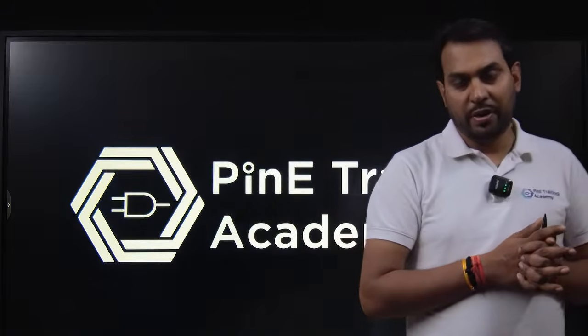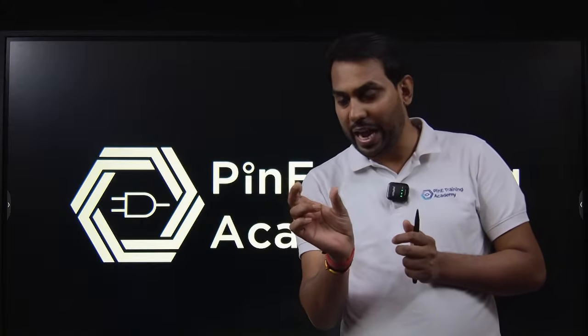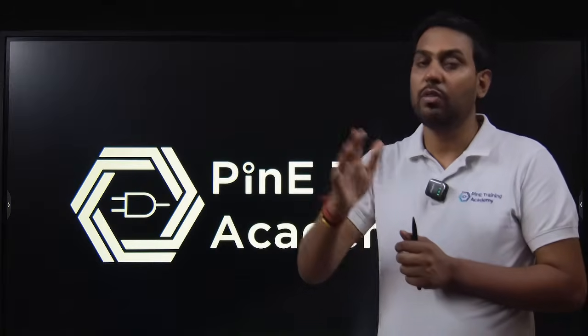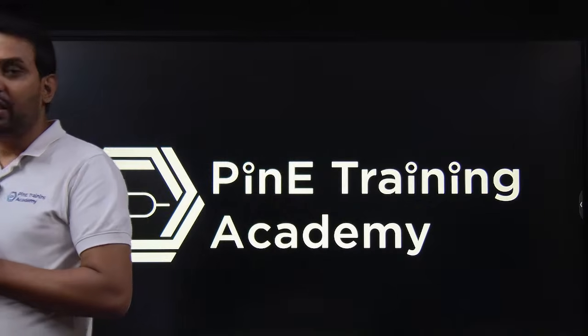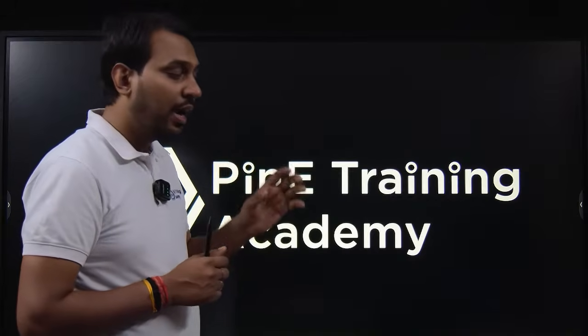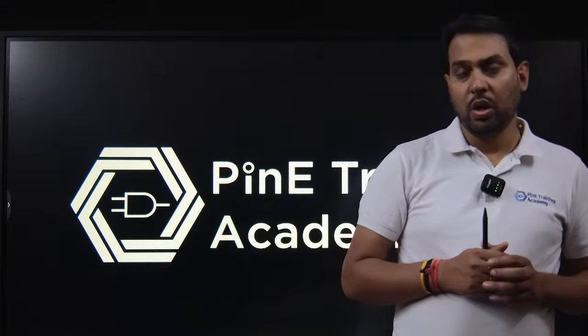After that we made one pulse and discussed that as the pulse duration decreases, the capacitor will not fully charge, and similarly the discharging is limited. So charging and discharging depend on the time constant of the circuit and also the pulse width of the input.